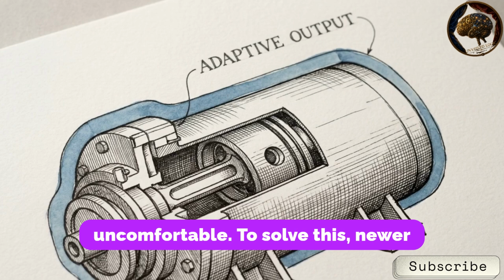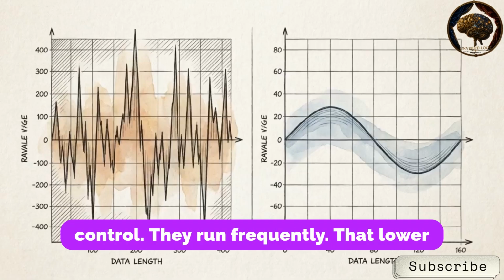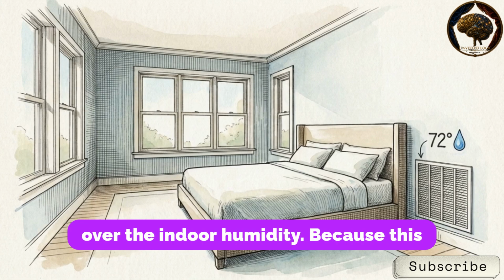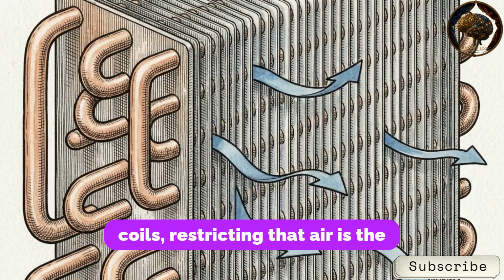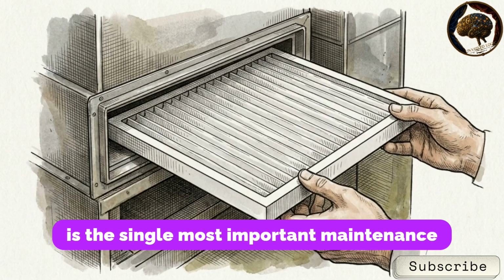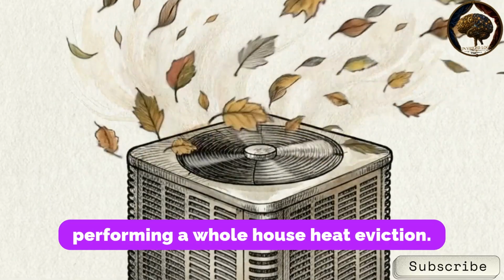To solve this, newer designs use variable capacity compressors. Instead of a system running at 100 miles per hour or 0, these act like a car's cruise control. They run frequently, but at lower, efficient speeds, often around 70% capacity. This maintains quiet, perfectly balanced temperatures and strict control over the indoor humidity. Because this entire heat extraction process relies on steady, predictable airflow across the coils, restricting that air is the fastest way to break the system. That is why changing the air filter regularly is the single most important maintenance task for a homeowner. When that central system kicks on, you're hearing a relentless, perfectly balanced machine performing a whole house heat eviction.